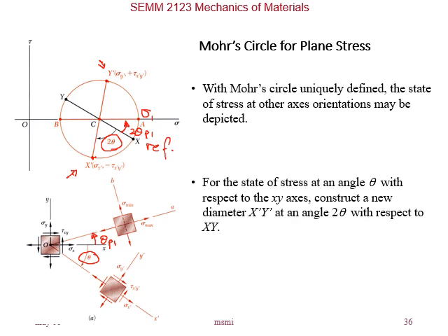So what are the values of the stresses on the stress element? They come from the coordinates of the points. That is x prime and that is x prime. The coordinate of the x prime point is equal to the stress values here. So you have a sigma x prime and tau x prime y prime. If it is positive or counterclockwise, this is counterclockwise, right? This is positive in our case. So you draw it counterclockwise. Over here, this is negative or clockwise direction, right?